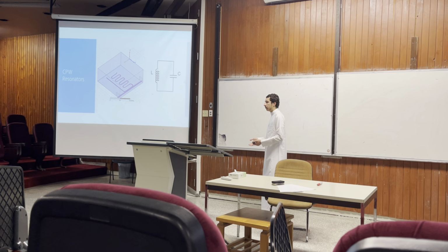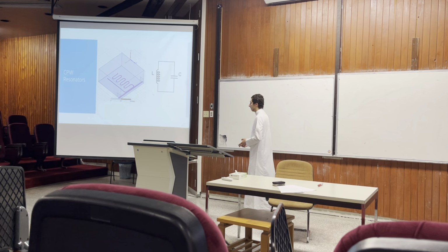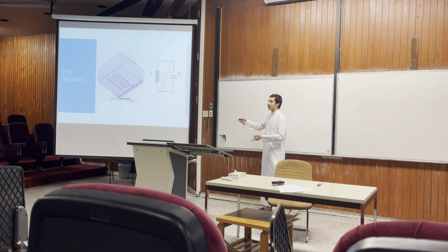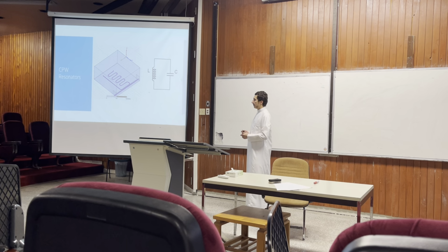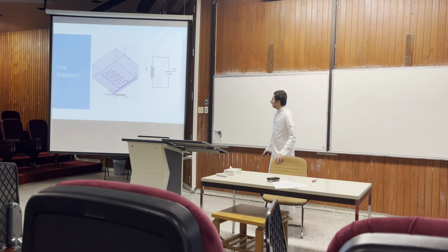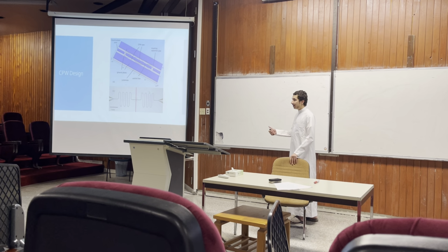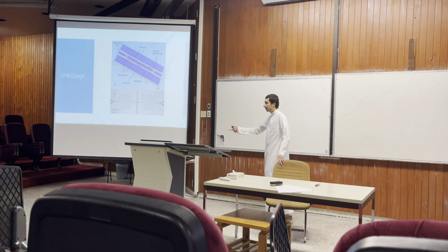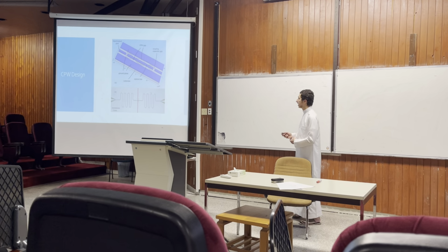And so what we do generally when we make measurements is we send a sweep of frequencies. So many different frequencies with small iterations between them, let's say. And so for this case, we use a harmonic oscillator, a normal LC circuit, because in this way it's just easier to fabricate, easier to deal with as well. And this is, let's say, a typical design of a coplanar waveguide resonator. And so we use them for reading, for controlling and manipulating our qubits as well. There isn't just one application for them.